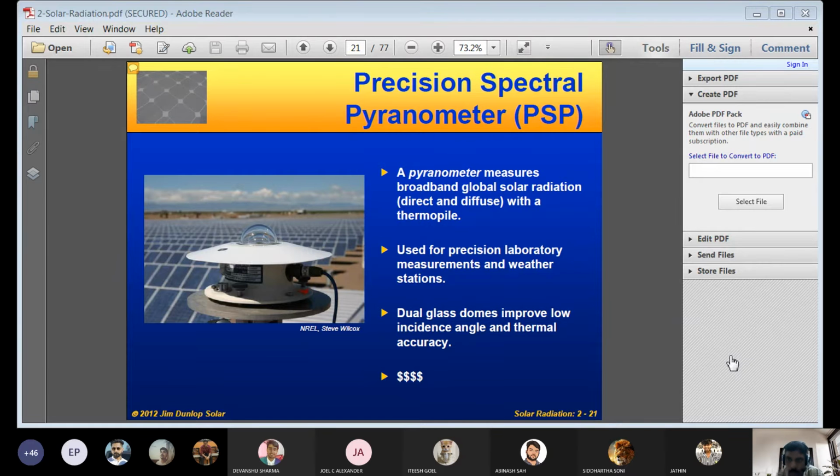Thermocouple, anybody? Nowadays you can buy some cooling elements from Amazon, Flipkart, etc. If you connect it to a battery, one side will become very cool, with aluminium, zinc, etc. Have you noticed? It is a thermoelectric cooler. So it constitutes thermocouples. Thermocouple means two dissimilar wires coupled. You take aluminium and copper, two pieces, and make a loop by joining these two ends. It is a thermocouple. Right.